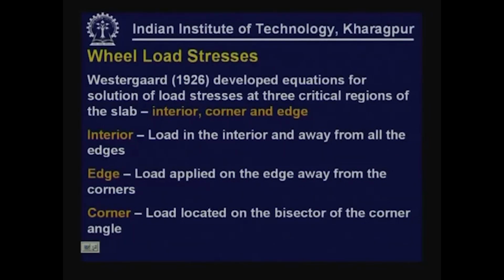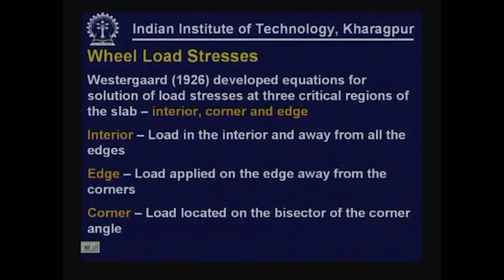But we will confine our discussions to Westergaard's solutions of wheel load stresses. Obviously, all the assumptions that go with Westergaard's solutions will have to be taken together. Westergaard in 1926 developed equations for solution of load stresses, as I mentioned, at three different critical regions of the slab: interior, corner and edge.